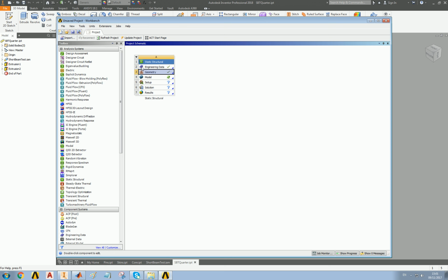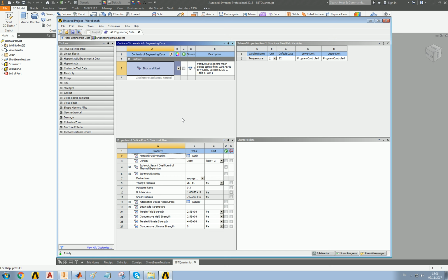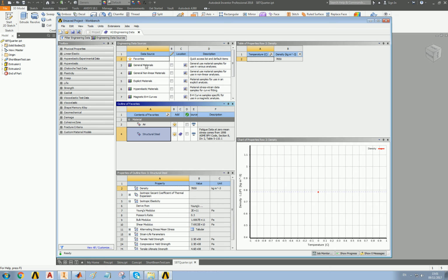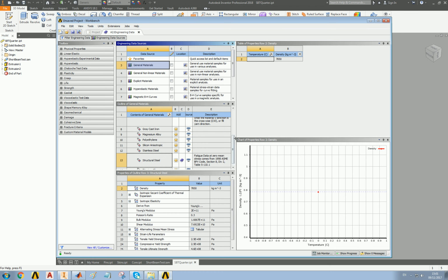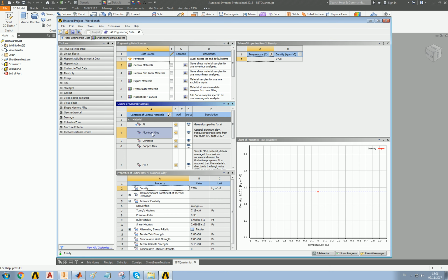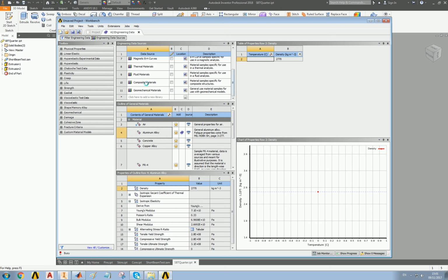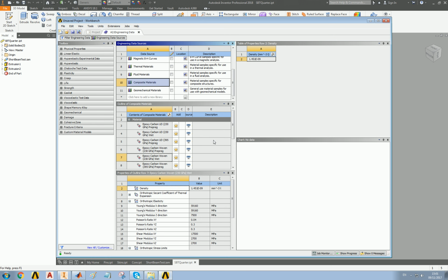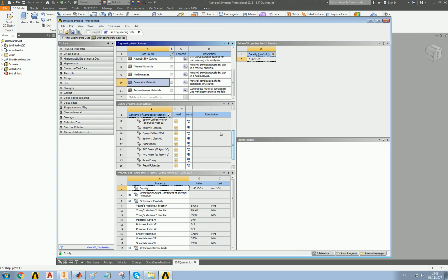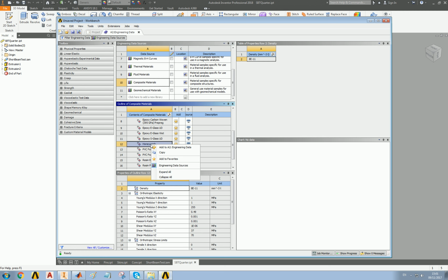Now before we do anything, this is a composite thing, so there are going to be 3 materials. Very different. We've got steel built in, we'll use that. We want to add in more materials, so let's go to general materials, add in aluminium, not too fussy about which. Add. But there's also a composite materials database, lots of epoxies, and what we're going to use today is honeycomb.